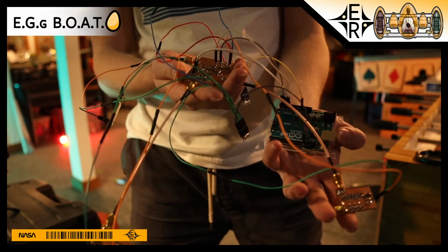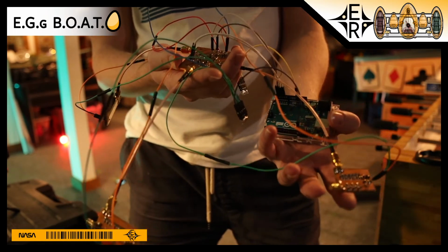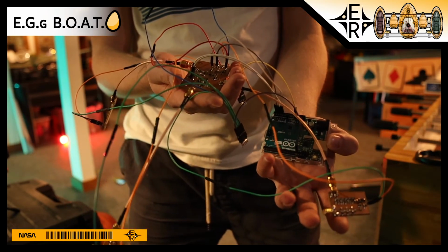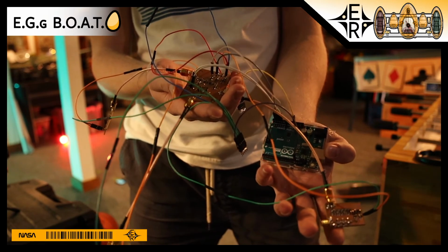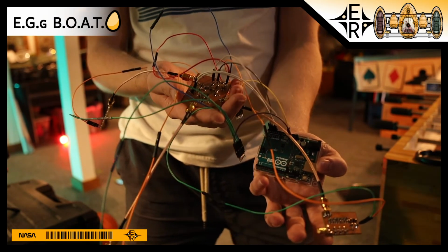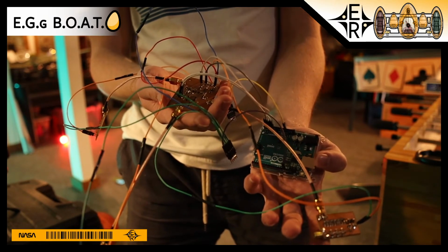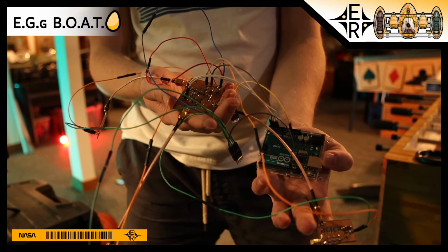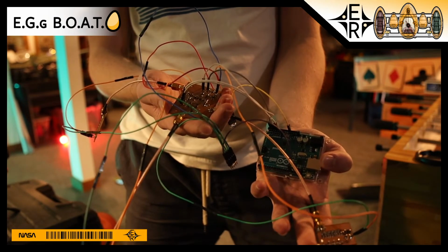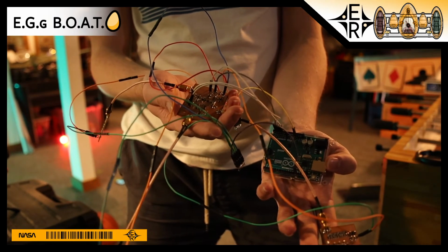It'll take those amplified sine waves and run them through a comparator, which will take them to a 0 to 5 volt digital level, meaning all the positive halves of the sine wave will go to the high value of a square wave, and all the negative halves will be the low value.